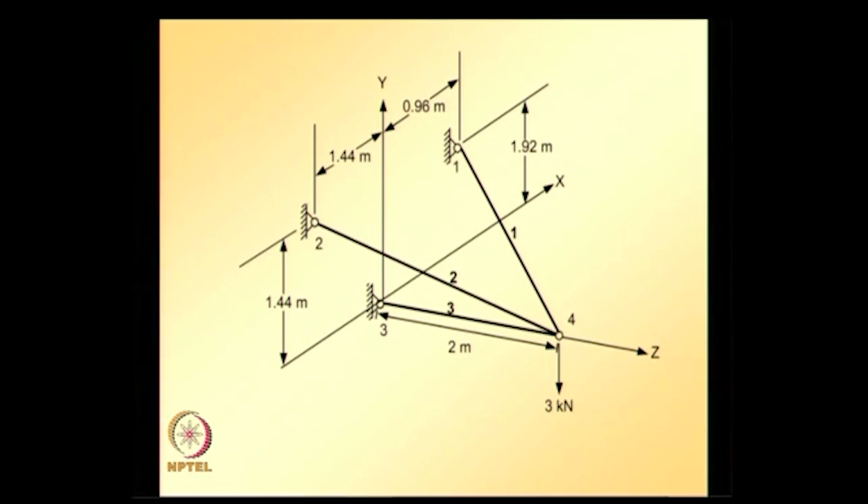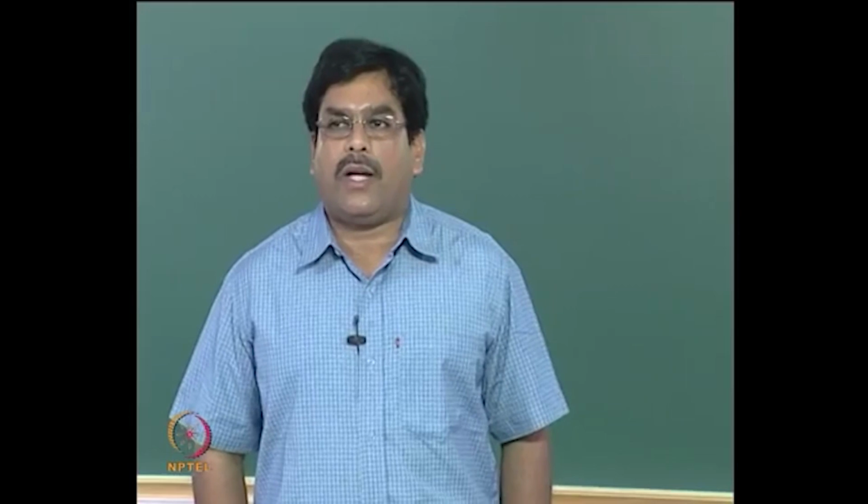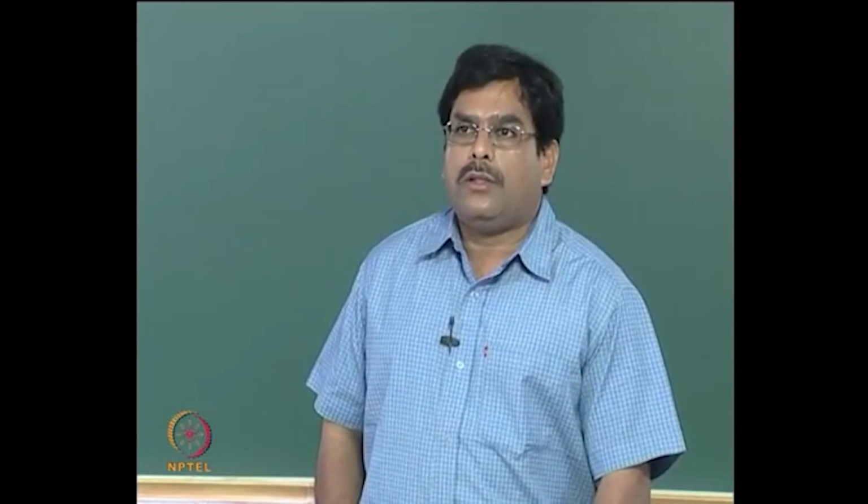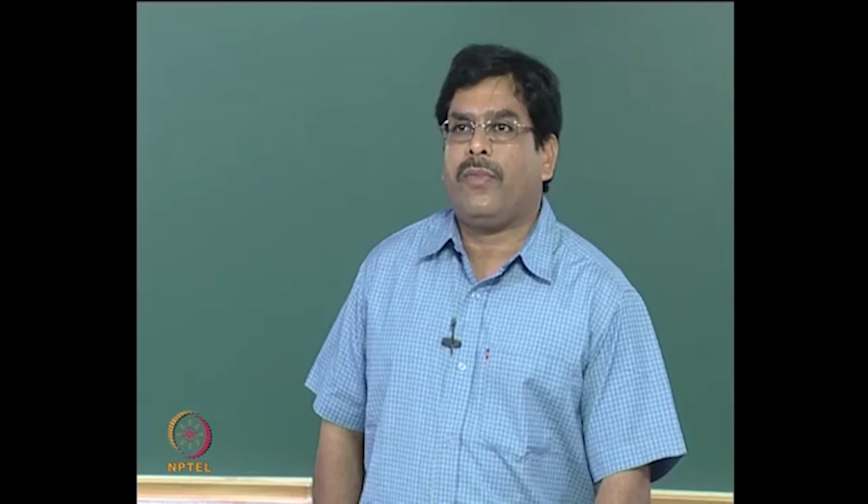And now, again for simplicity, the element equations are directly written in terms of global degrees of freedom while taking into consideration the boundary conditions. The unknown reactions at the ith node corresponding to 0 displacements are identified as r xi, r yi, r zi, where i takes values 1, 2, 3. It is similar to what we did for 2D plane truss elements.